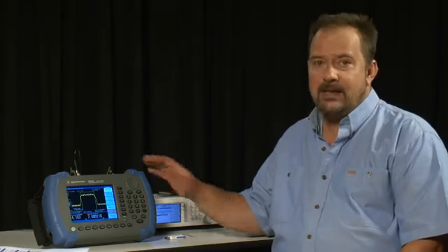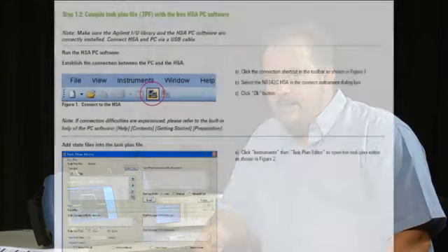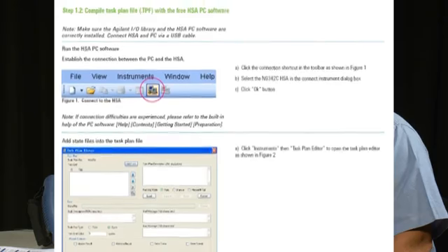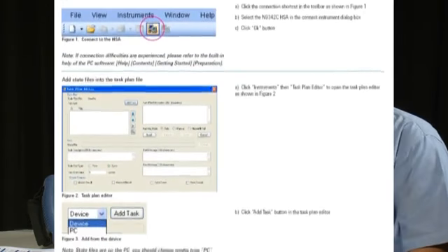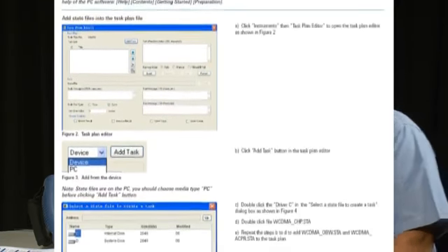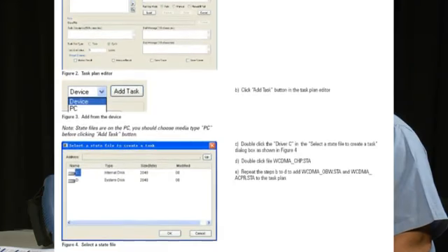Sometimes I get asked how we can simplify and even automate a series of predefined measurements that a rigger or less experienced technician can perform automatically out in the field. Well, the new option TPN task planner capability of the N9342C allows us to do exactly that by stepping the operator through a series of up to 20 tests and automatically saving the measurement results of each test into the instrument's internal memory without needing a PC out on site.